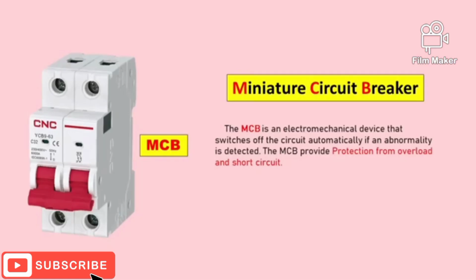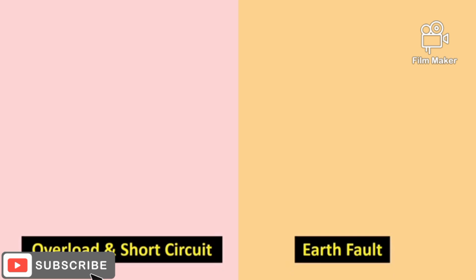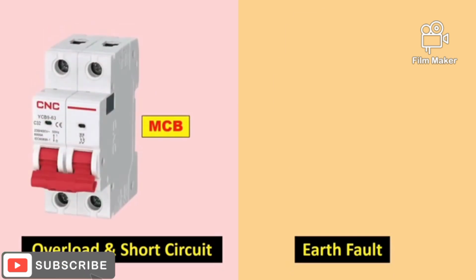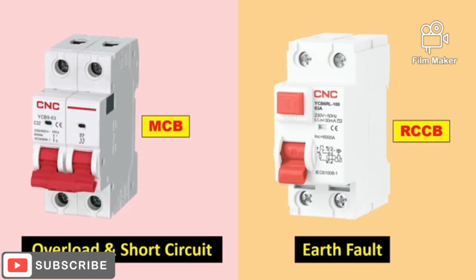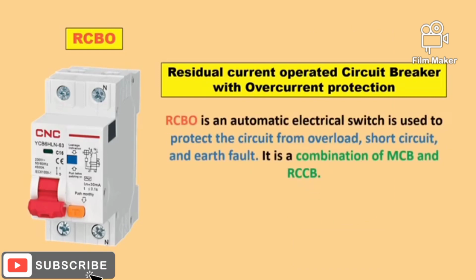Like I told you in the starting that the MCB we have, MCB provides us protection from overload and short circuit. After this I told you that the RCCB you have, RCCB provides protection from earth fault. Now if we want protection from earth fault, overload and short circuit, then we have to use MCB and RCCB, both these devices. But if you don't want to use two different devices, and instead by using only one device you want all the three protections, then in this condition you have to buy a RCBO. So through RCBO you will get overload, short circuit and earth fault protection.